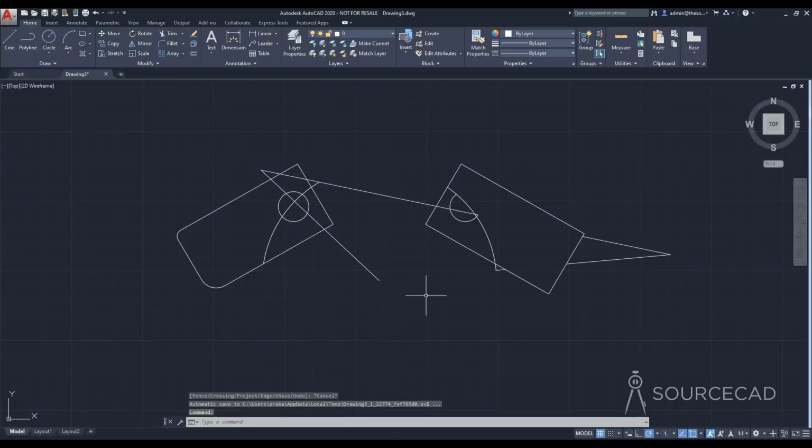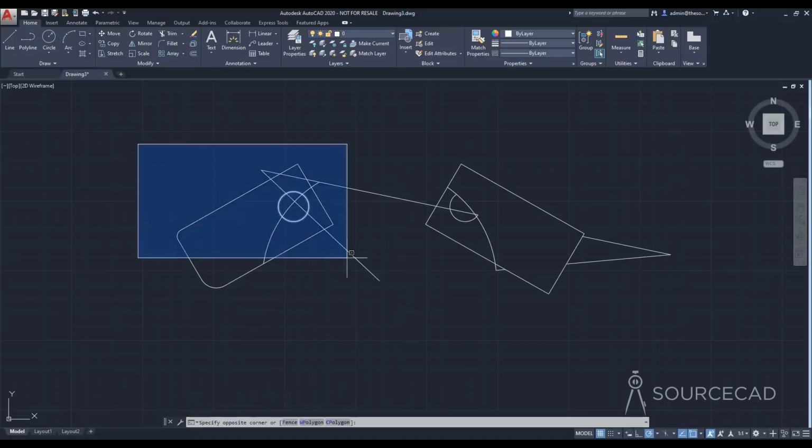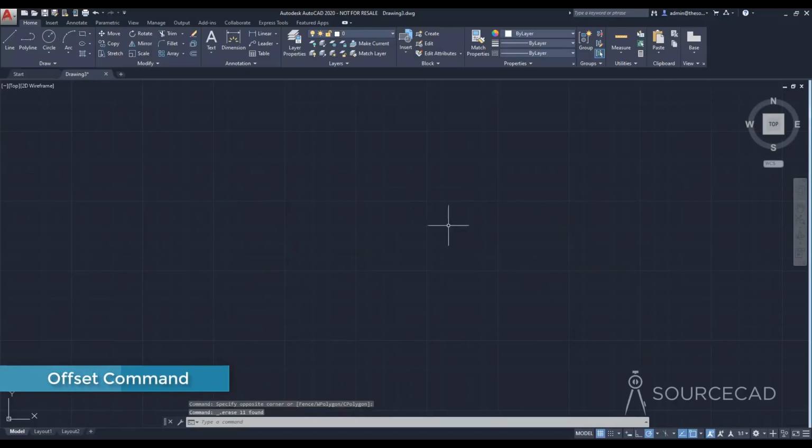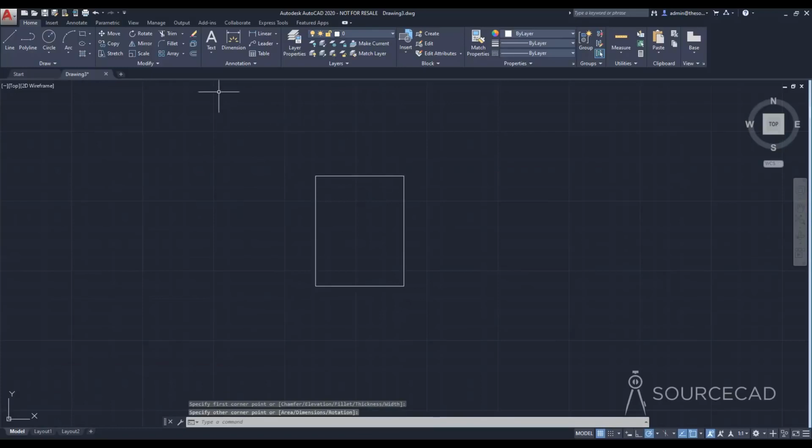And that's trim tool. Now, finally, let's talk about a tool called offset. So I'll go to rectangle and I'll add a fillet of radius 10 on this corner and I'll press enter. Pressing enter will just repeat your last command. And I'll select this one. Okay, there we have it.